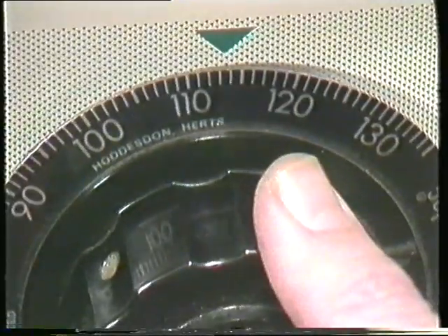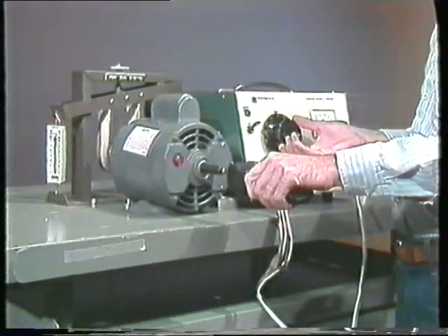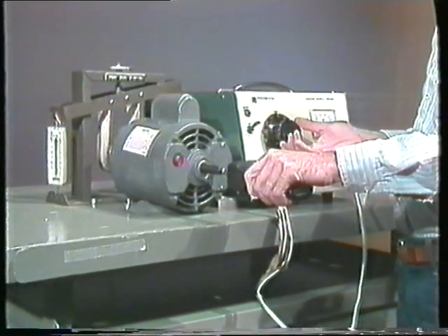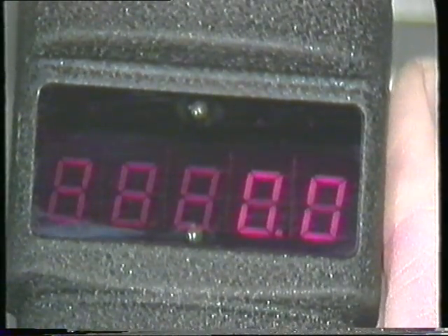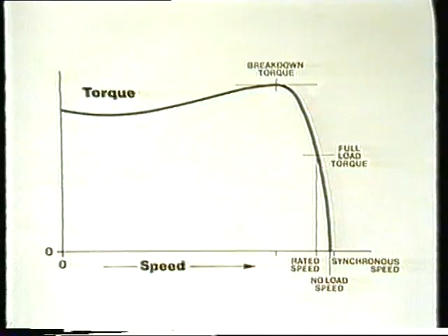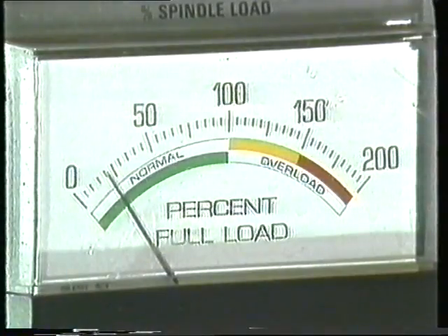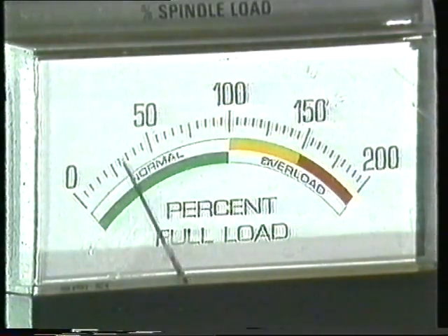Induction motors are especially likely to stall if line voltage is a little low. A line voltage drop of only 20% can reduce breakdown torque so much that the motor will stall even with its normal load. When the motor is stalled, it exerts the same amount of torque that it exerts trying to start its load. On almost all motors, startup torque is greater than full load torque. That means that most motors can start and run under overload conditions.